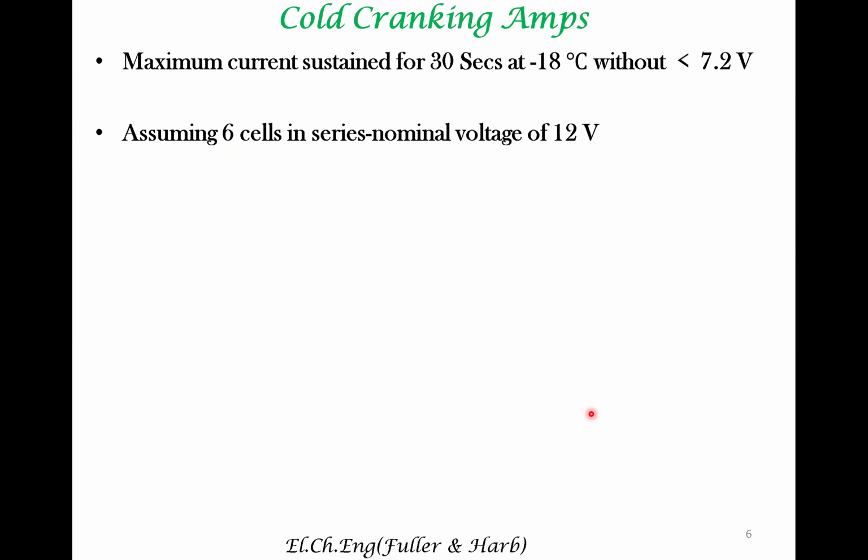So this is an additional terminology, rather a jargon, but it's an important jargon for you to understand. This is called cold cranking amps. There are three things here. Obviously, this has to do with current. Cold, because we want a battery to be operational at a very low temperature.